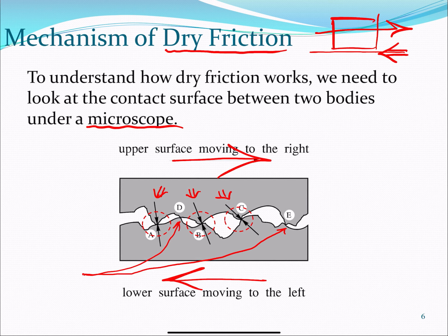When you reverse the sign of the movement, when you push the box on the other side, then the other points of contact will engage, perhaps. So all in all, if you have just a small body with a few points of contact, you will see that the friction force is not the same if you push from one end to the other than if you push from the other end to the one end.